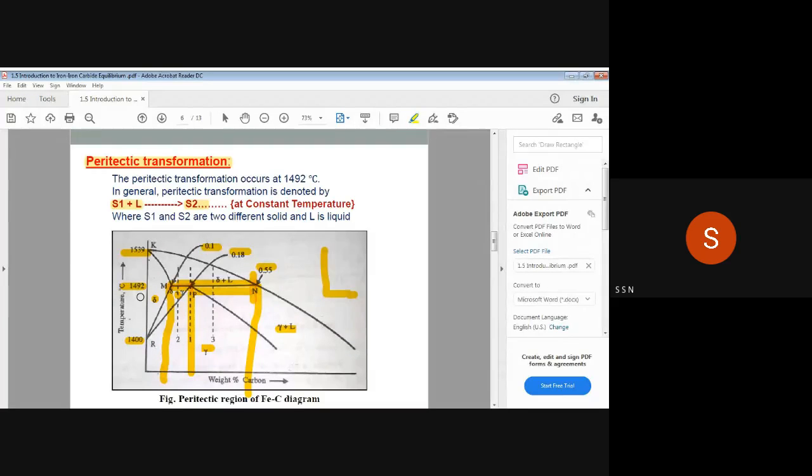So through this heating, cooling, and getting the new microstructure, we are actually achieving the different properties of same alloy, because here alloy is iron and carbon mixture. So for same mixture, we are getting different properties. Why it is possible? Because we are getting different microstructure for different composition and for different temperatures.